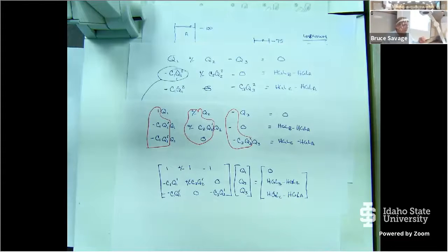Well, this is kind of the same way, except that when we linearize it, remember that q squared, it doesn't matter if it's negative, it becomes positive. And likewise, if I take q times q, because I have q old and q new, if they're both negative, they become positive. And now I've killed the direction of my system. So I have to have a way to maintain direction in my system. How am I going to maintain direction so that if I'm solving this and it says you've got one of the flow rates backwards, it will come out negative in the end? So that's another numerical trick.